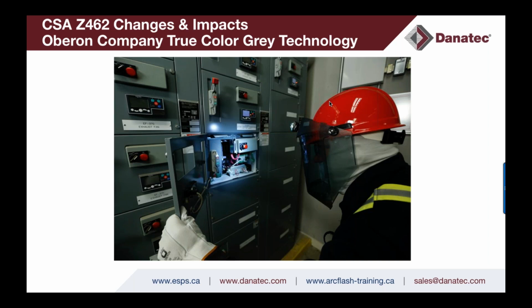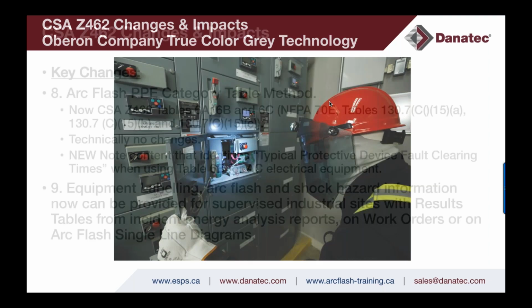So then again, the PPE for an incident energy analysis study shall have two choices: 1.2 to 12 calories or greater than 12 calories. Two selections that are available to the qualified electrical worker, two different arc ratings your company should procure and have available to the workers.